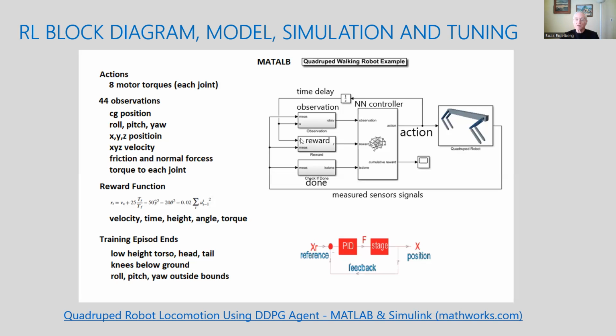Extremely important to realize that the difference between the PID and the reinforcement learning is that in a PID, we set up the reference point that we like it to move, and that's what the PID is making the output do. Over here, we set up the reference, but there may be due to observed variables of the environment different ways of acting.